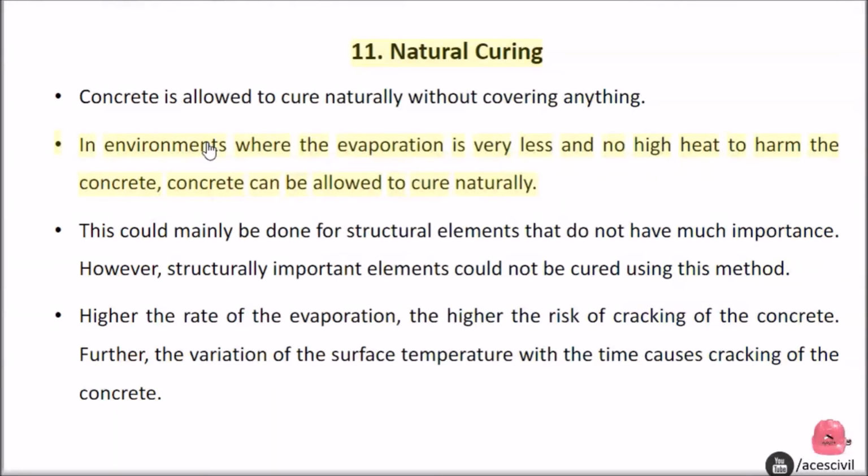Natural curing. Concrete is allowed to cure naturally without covering anything. In environments where the evaporation is very low and there is no high heat to harm the concrete, concrete can be allowed to cure naturally. This could mainly be done for structural elements that do not have much importance. However, structurally important elements cannot be cured using this method.